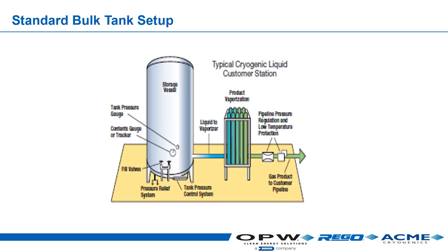When it goes to the house line, with this cryogenic system and how it's set up, the biggest thing is flow rate. What is the end user's flow rate? What pressure do they need? And what temperature do they need? Those are the three things the final line assembly regulates for you. From wherever the tank is located outside, you also have to factor in the distance of all the piping and where the product is actually being used. The key is you've got to size the vaporizer correctly based on the flow rate, the pressure, and the temperature. It's mainly the flow rate.